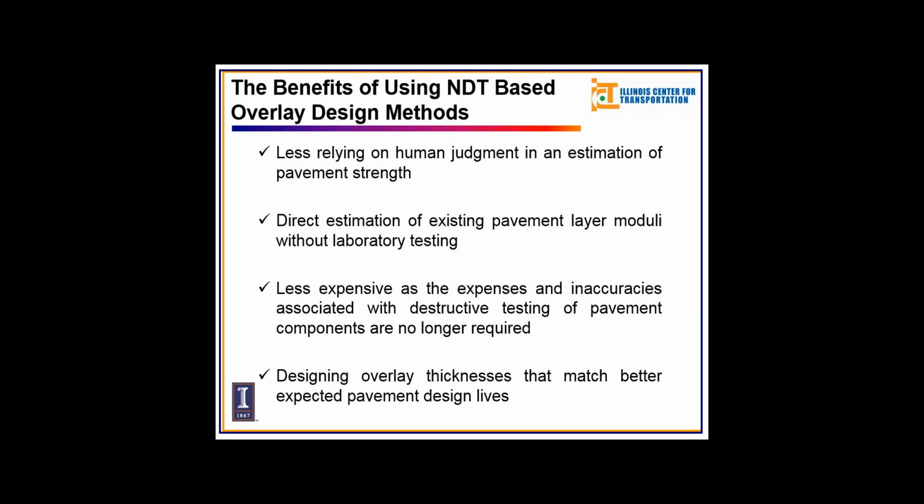Then we are directly estimating the existing pavement layer moduli from the field without doing any kind of laboratory testing. And also it's less expensive, as the expenses and inaccuracies associated with destructive testing of the pavement components are no longer required. And since we are designing an overlay thickness based on a proper structural condition assessment, whatever we are coming up with is expected to better match the pavement service life.